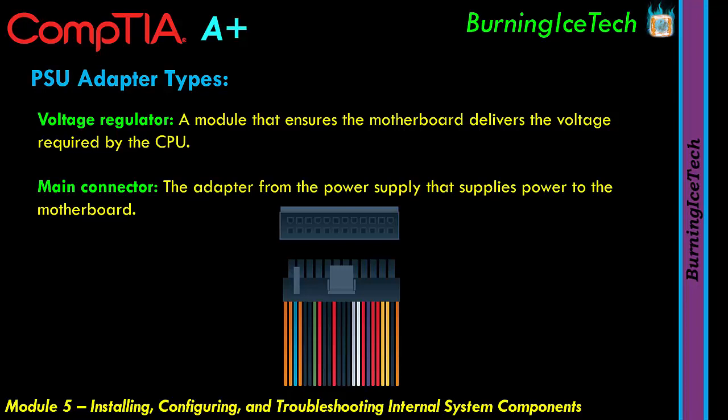And in the old days, I want to say 15, 20 years ago, it used to be only 20 pins. And then at some point in time, you'd find power supplies started coming out with 20 pins with a 4-pin extra one, which you could detach. If you look at the bottom picture, there are actually 2 pictures there. You'll find it's got 2 little clips on it. So even though it's not possible to see it in this picture, that one is most likely one that's detachable. So the 4 pins on the left-hand side can probably detach from the other 20 pins on the right-hand side. So you can actually split it.